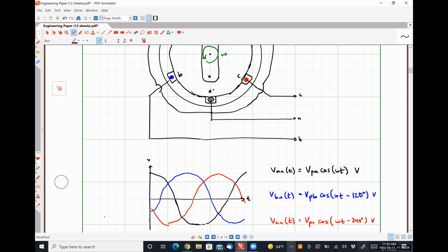It's going to run off that, at pretty much the exact same frequency unless we put a load on it, which will cause it to slow down a little bit, and then in steady state, it's going to rotate at that frequency forever. When you hook up a VFD and you're doing some analog signal processing, that's where pulse width modulation to generate sinusoidal waves pieced together from square waves comes from.